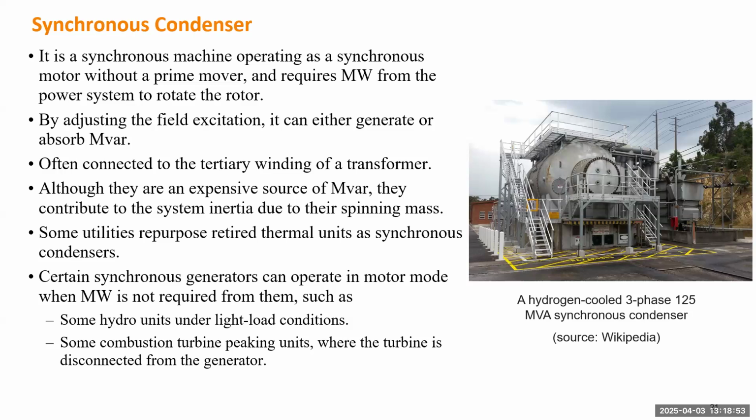You still have an exciter, but you don't have a governor. You don't have any turbine models. But you keep the detailed synchronous generator model together with the exciter model, because a synchronous condenser has much better performance than any other controllers. So if that can verify your concept, then you can move to each individual controller for voltage.